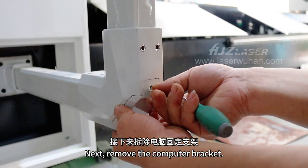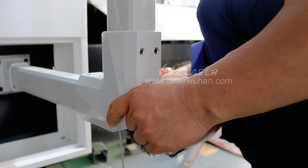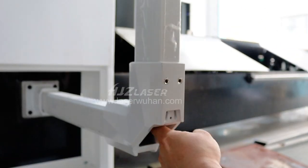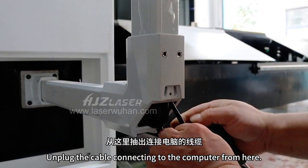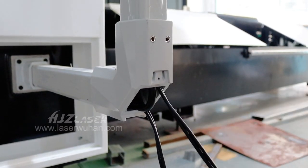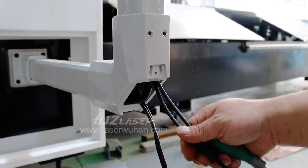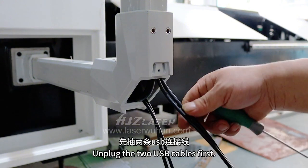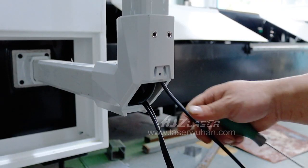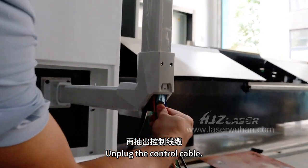Next, remove the computer bracket. Unscrew the 2 screws here. Unplug the cable connecting to the computer from here. Be careful not to use too much force. Unplug the 2 USB cables first. Unplug the control cable.